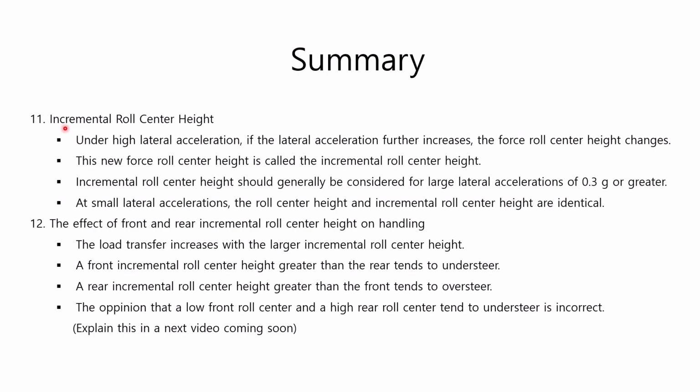Incremental roll center height has been explained. Under high lateral acceleration, if the lateral acceleration further increases, the force roll center height changes. This new force roll center height is called the incremental roll center height. Incremental roll center height should generally be considered for large lateral accelerations of 0.3 g or greater. At small lateral accelerations, the roll center height and incremental roll center height are identical.